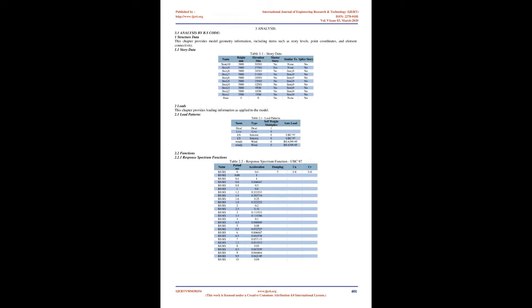The dynamic effects are also found by response spectrum method. All the parameters like story displacement, story drift, base shear, overturning moments, acceleration and time period are calculated. After comparing all building shapes, results concluded which section is convenient and whether seismic or wind effect is critical.